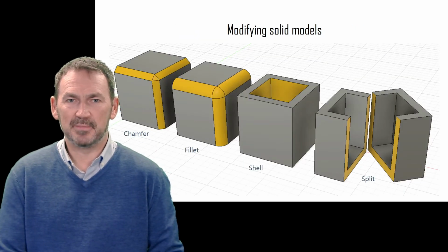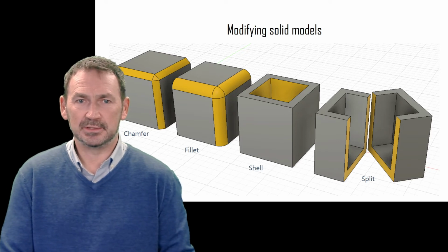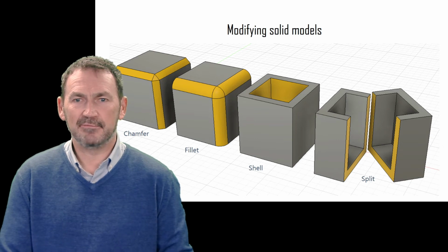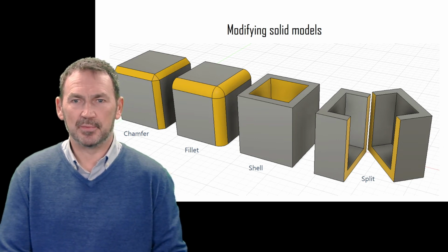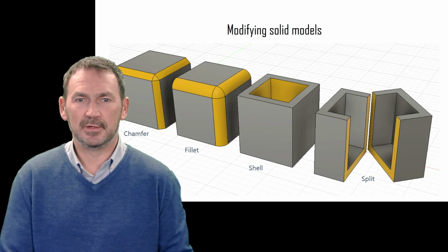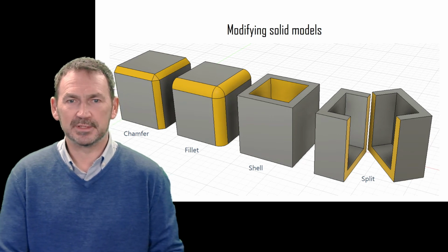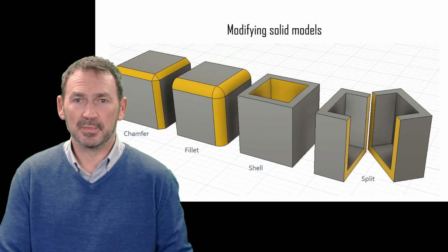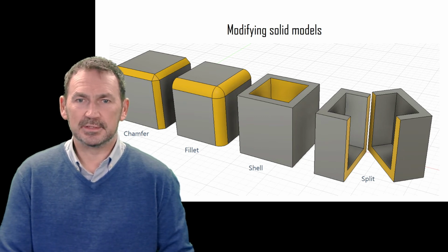Once solid bodies have been made, they can be changed using a series of modification tools shown here. Fillets and chamfers take the hard edges of solid bodies with either a slant or a curve. The shell tool requests an opening surface to be selected before the inside is hollowed out like a Halloween pumpkin to leave an equal thickness inside.